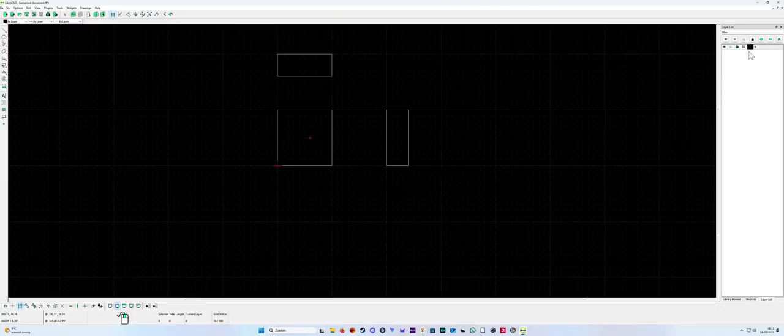And now I push on the plus sign here. Then I open a new one, and then give it a name. Let's say center line, black and white. The center line must always be thinner than the drawing lines, of course. So I put it on 0.05 millimeters, and then here, you can see it, center line, small. You can also do center line large, tiny,